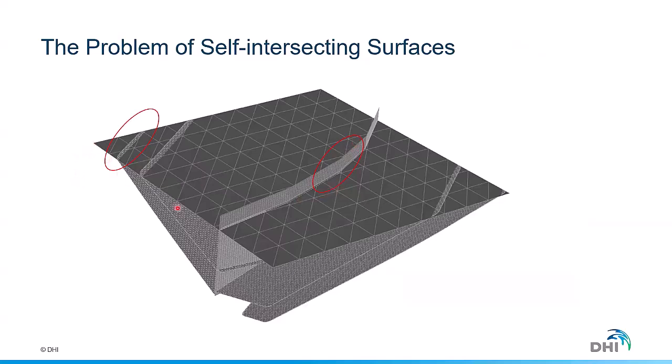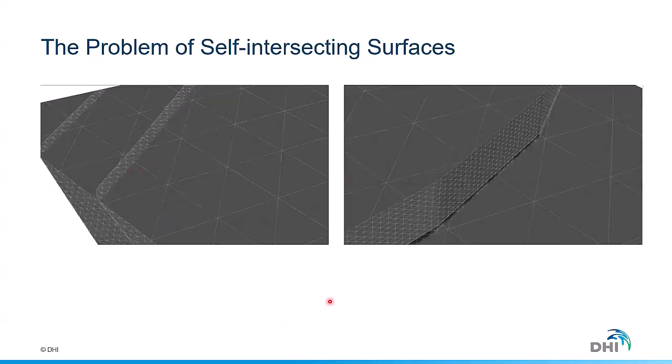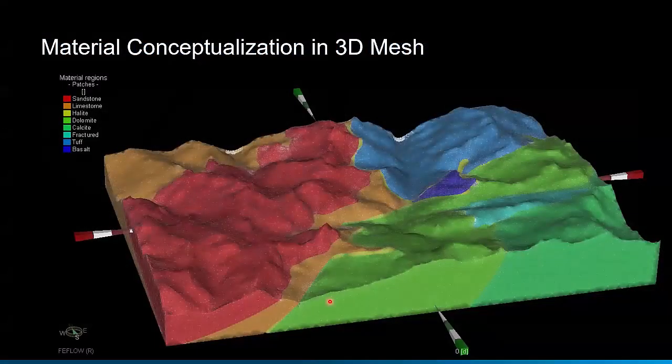Here you have coarse triangulated surfaces, which probably come from a geological contact, and then you have a number of surfaces which are very well refined, potentially from a fault model. So they were discretized differently. The resolution of the surfaces does not fit, so the mesh generator takes this but cannot do anything. How we work around this situation is what we are going to discuss.